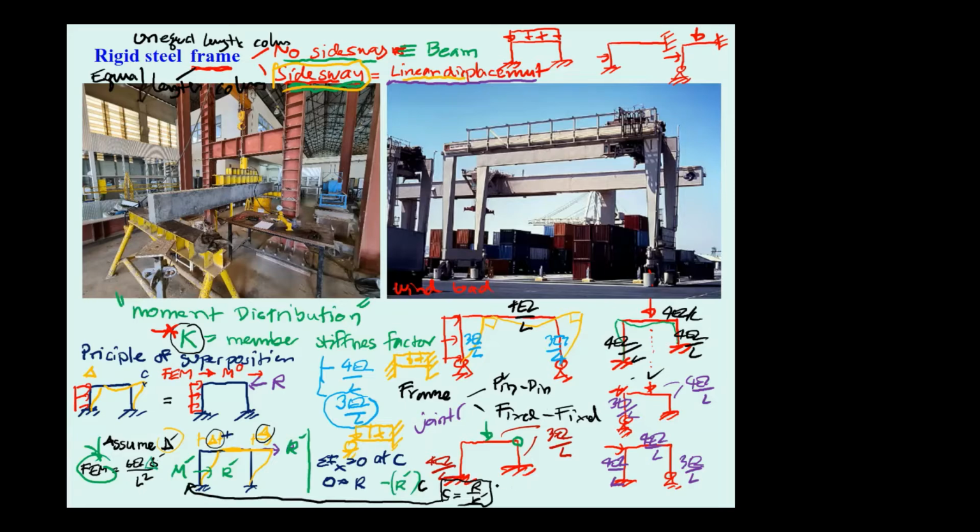Okay, so now the moment here is going to be equal to the moment here, M super naught, plus C times the M prime. You will have the moment that occurs in your problem. Okay, the computation is going to involve two moment distributions.